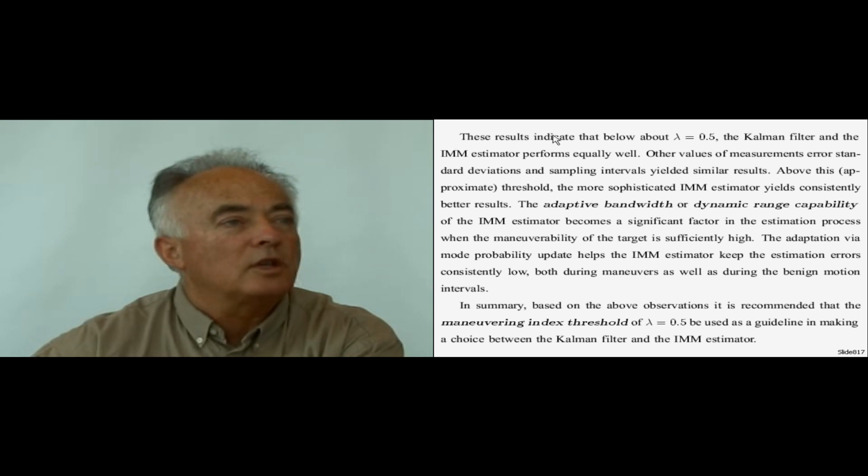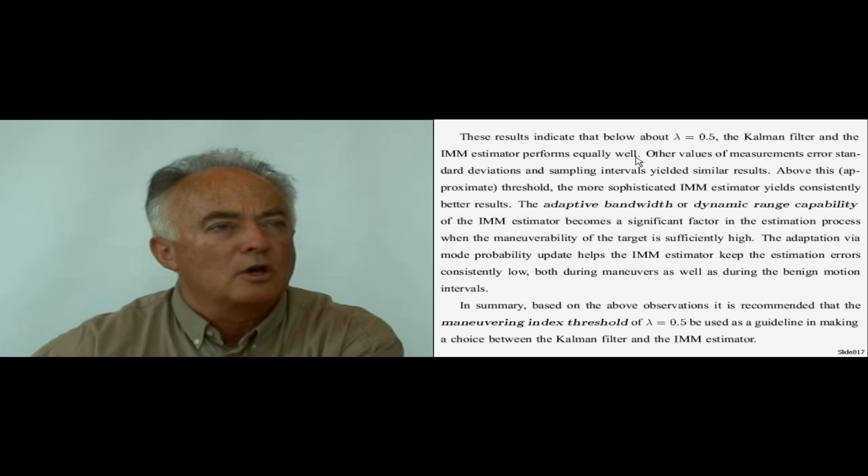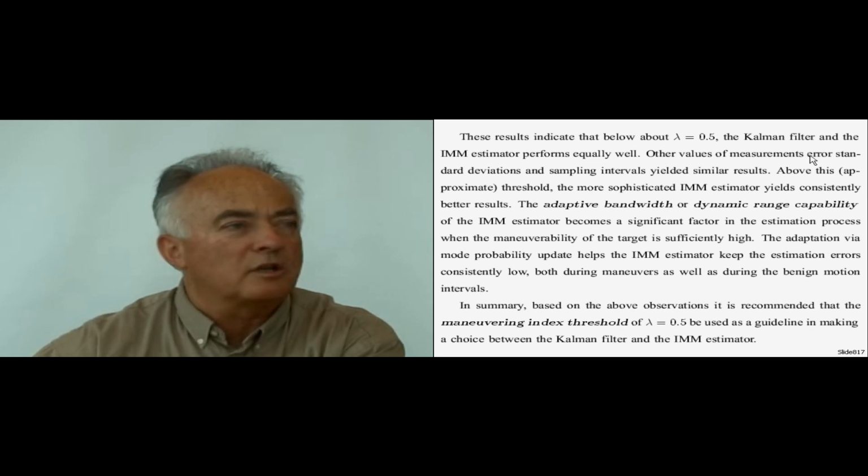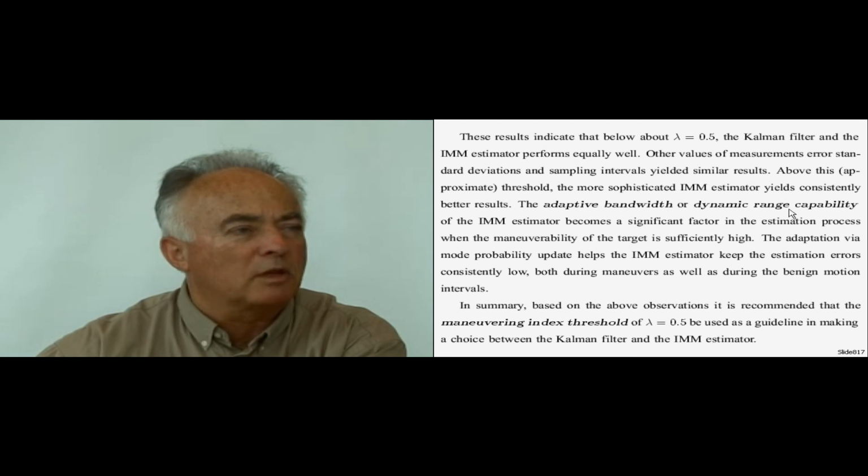These results indicate that below 0.5, the Kalman filter and the IMM estimator perform equally well, and there is no need for an IMM. Other values of measurement error standard deviation and sampling intervals would yield similar results. And this is the approximate threshold above which the more sophisticated IMM estimator is consistently superior due to its adaptive bandwidth or dynamic range capability.